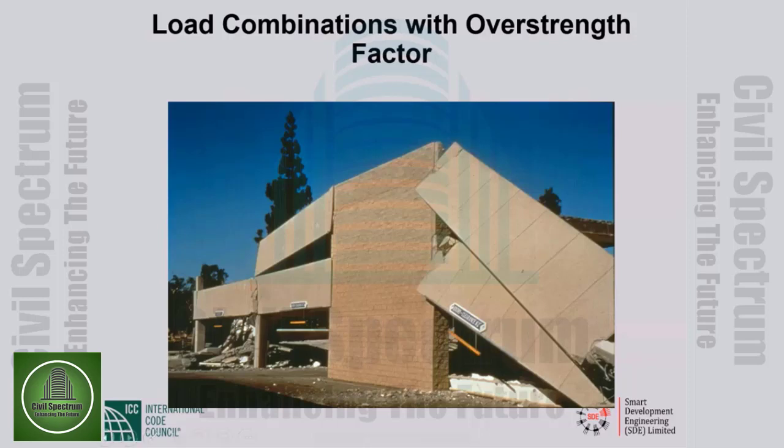However, as we approached the parking structure, this shear wall at the front was not only standing, it looked surprisingly good. Nothing had happened to it, not even cracking. And the question naturally arose, how come it looks so good? You know, everything else around it is down on the ground, and this thing is standing up in all its glory, looking like nothing has happened to it.